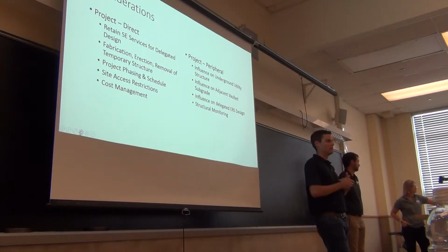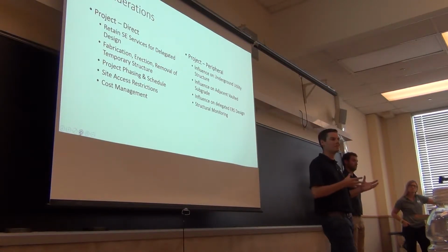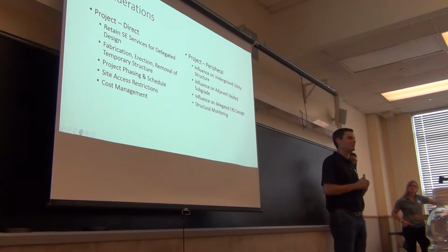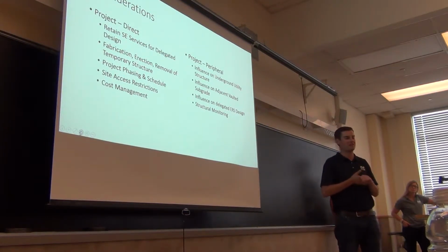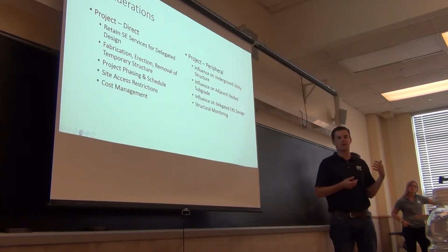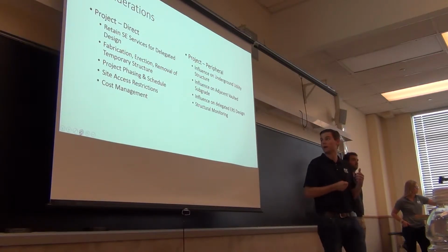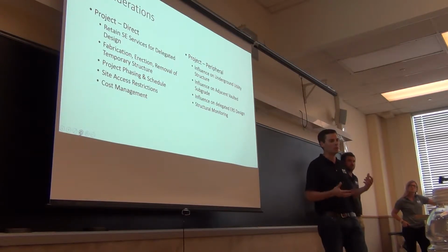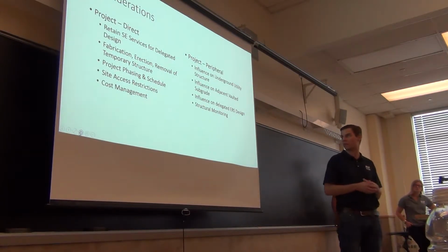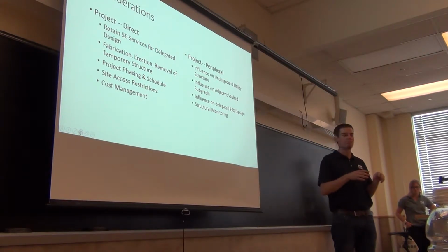So there was a specialized engineer that we dealt with. It wasn't the same one that did the shoring design, but he specialized in vault analysis of subgrade structures. So he did a lot of review for us on this project, verifying that those structures were able to take the surcharge load. We actually did not run into a situation on this job where we had to then shore the interior of the vault. So it was reviewed, and determined that those were adequate based on the new load points.